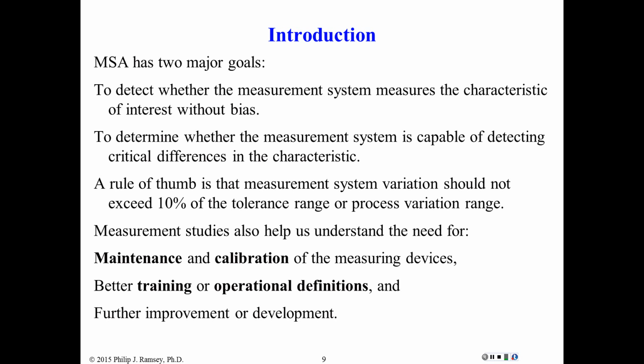So if I'm using a tape measure and it's off by an inch, every board I measure is actually going to be either an inch too long or too short. So if I use the tape measure to decide where to cut, the boards are always going to be too long or too short, and the problem is the measurement system was inaccurate. So accuracy is of interest. And then generally we worry about precision or noise in the measurements. In other words, if we take repeated measurements with this measurement system, how much variation do we see among the repeated measurements?